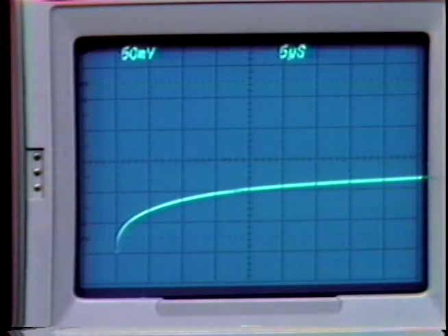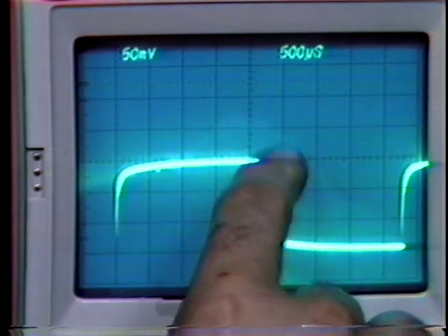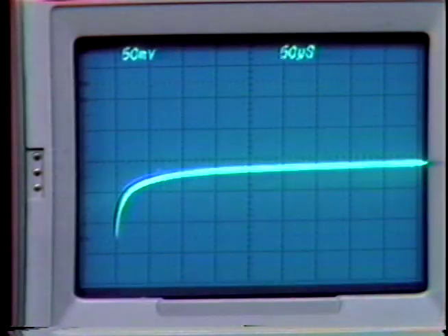The effect of using the approximation to the 1 over radical S roll-off is that we end up with an open loop transfer function that has poles and zeros alternated along the negative real axis. And if we draw a root locus diagram for that, we end up with a very large collection of pole zero doublets, in this case 11. And we get a very, very long tortured settling to final value. And we can see that final value has not even been reached here yet.